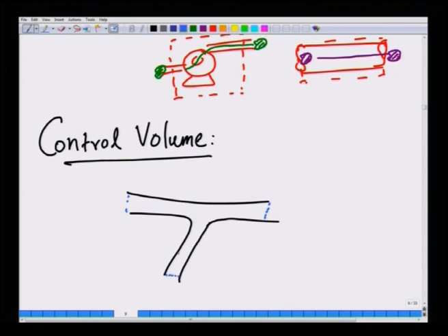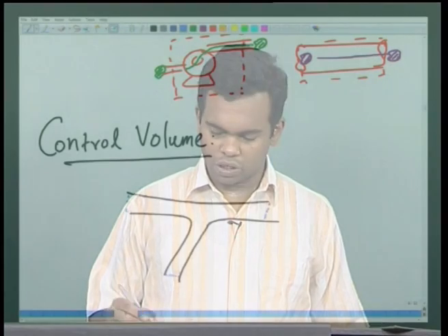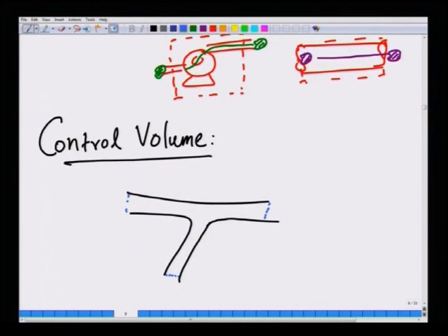It is not a physical boundary, but it is merely that surface that demarcates the region of interest from outside. It is called the control surface, and there are also these physical boundaries comprised by the wall of the tube. You can identify this as your region of interest, but fluid continues to come in and leave. If you consider a patch of fluid, it will come and then it will leave. It may not stay in the same physical region of space; it will continue to move.